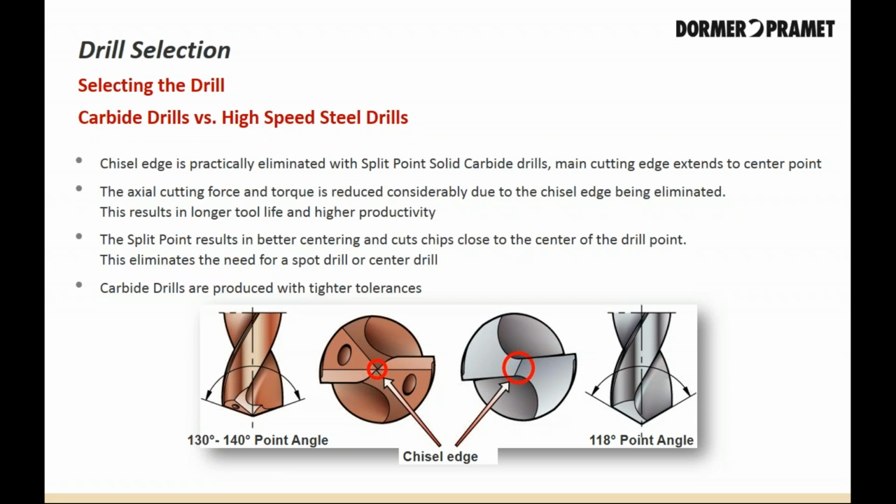Straightness of the hole. Solid carbide drills are stiffer than HSS drills, and there's more precision symmetry in the manufacturing of these tools. This enables us to guarantee the straightness of the hole when drilling with solid carbide drills. However, there is a risk of drill breakage in the case of longer solid carbide drills because of the brittle nature of the carbide substrate. In typical operations, the reach should not exceed 12 times D.